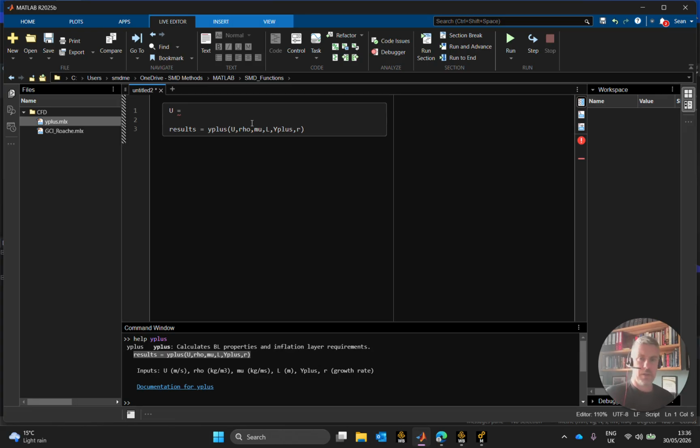However, where we're looking to take a lot of these corners, I need to question myself on what is the speed that I'm looking to generate this downforce at. It's not at them high speeds. I am interested in the downforce generated at high speeds, but that isn't where I'm looking to generate lap time. I'm losing lap time there. Where I'm looking to generate lap time is the application of downforce on corners taken at particular speeds. So we need to decide what speed we're going at.